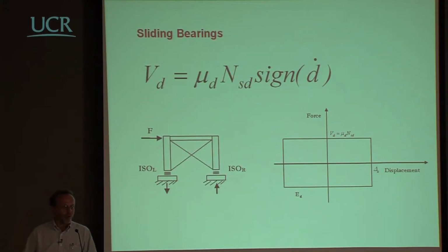It's not a control device, but in a way you have something where, if you look at a force displacement plot of something like this, the force that you are going to have here is essentially a function of the vertical force multiplied by the friction coefficient. And consider also the fact that even during a response to an earthquake, you are certainly going to have a larger vertical force here and a lower vertical force there, but the total force will remain the same.